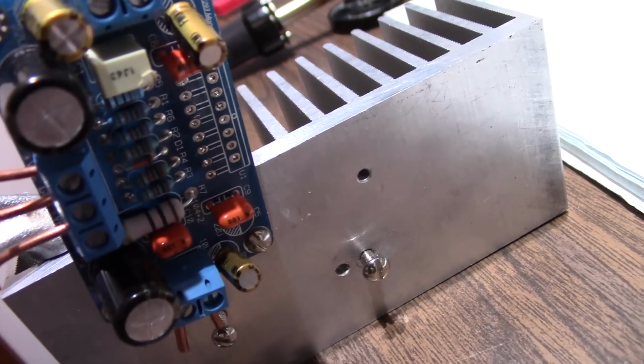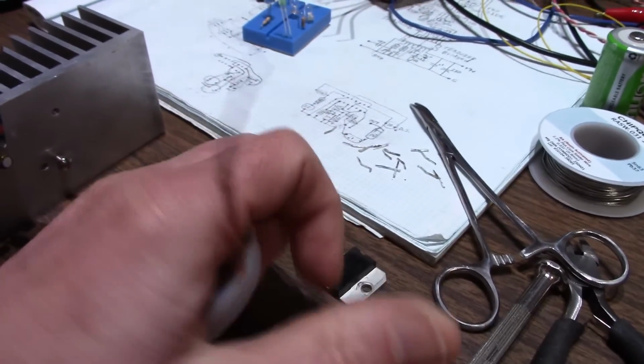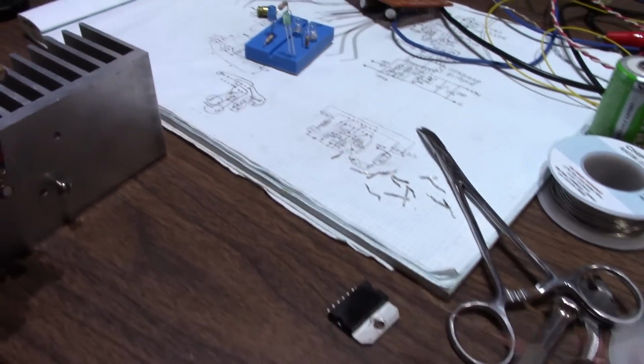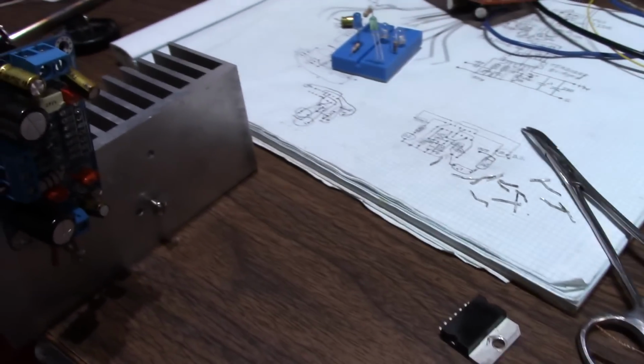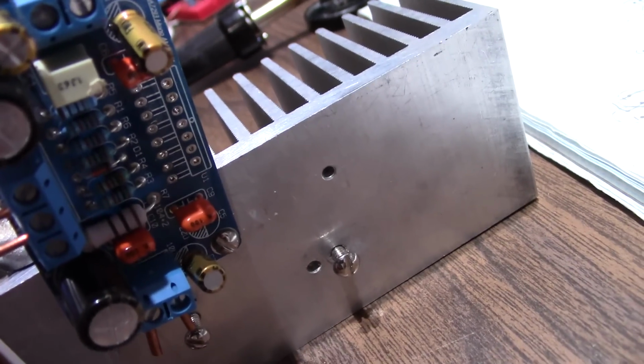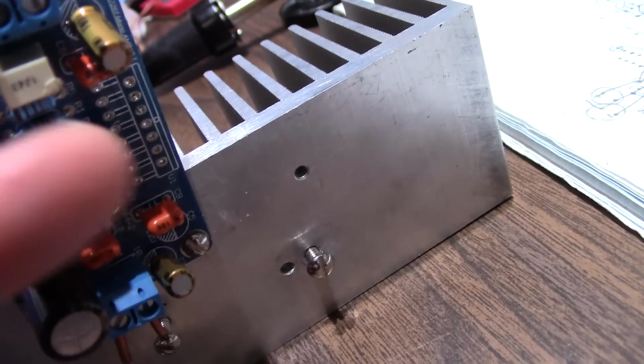Okay, I got the chip out of there. Still got to clean the holes out, but I had to sacrifice it. So I added flux to my desoldering braid to help me out. It really pulls the solder out, but those double-sided boards with those vias, you just can't get all the solder out of there.